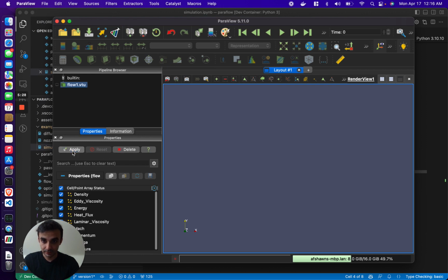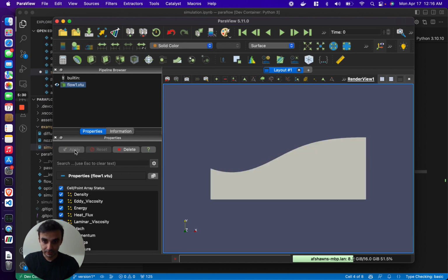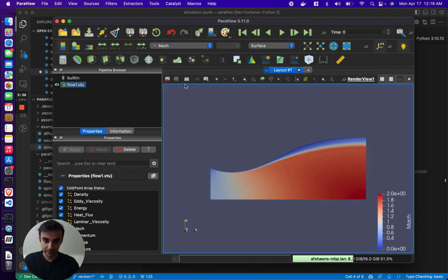So if you go here, this is essentially the result. If we take a look at the Mach number, because it's a rocket nozzle, the whole point is for the Mach to get higher, so that's why it's in red. The goal would be to perturb these control points for the geometry until you get an efficient and target engine nozzle that you want for your assembly. You can do this for diffusers as well, and keep tuning these points until you get something that is optimal. That's the idea of this project.